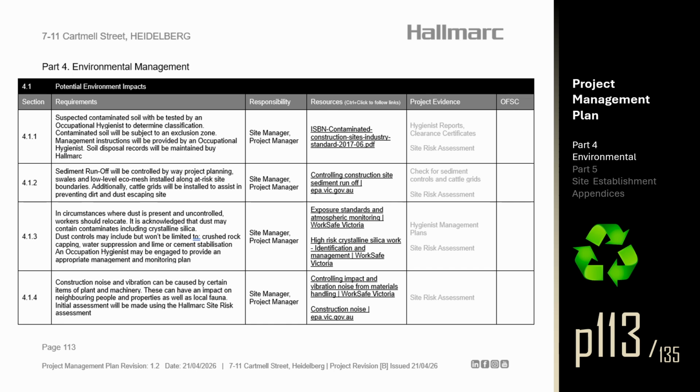Section 4.1.2. Sediment runoff will be controlled by way of project planning, swales and low-level eco-mesh installed along at-risk site boundaries. Additionally, cattle grids will be installed to assist in preventing dirt and dust escaping site.